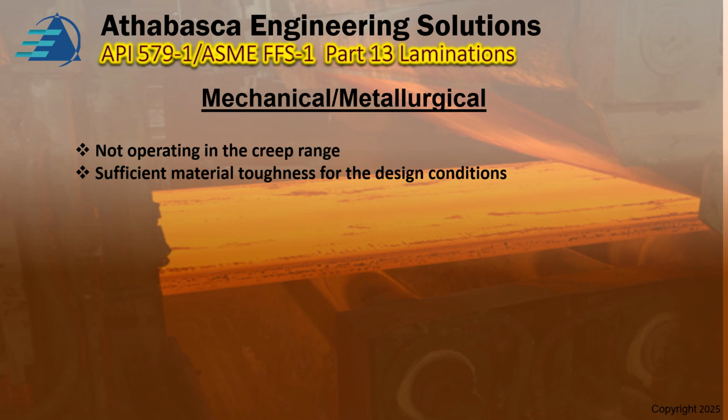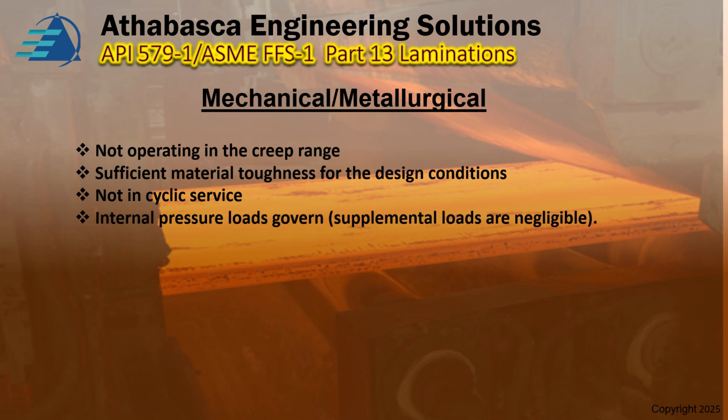The second one is we check whether this was in cyclic service, and it's not. The internal pressure loads govern, which means the supplemental loads, like bending and so on, are negligible.